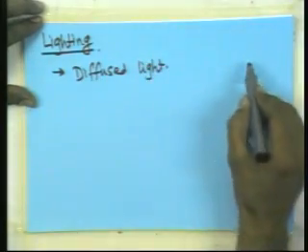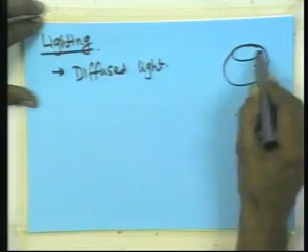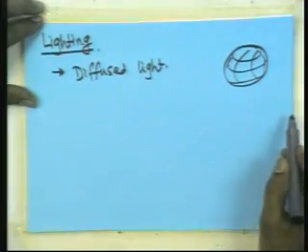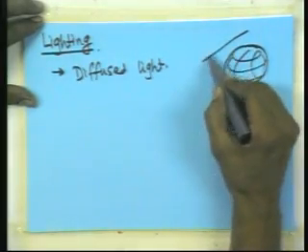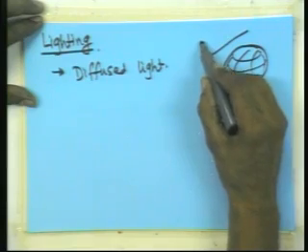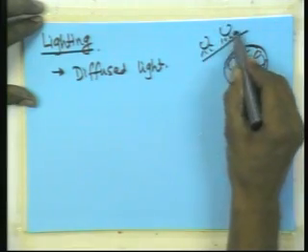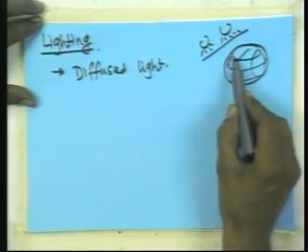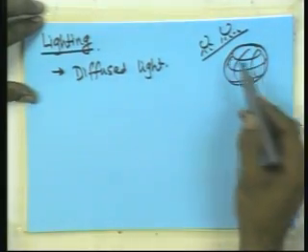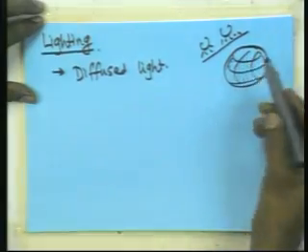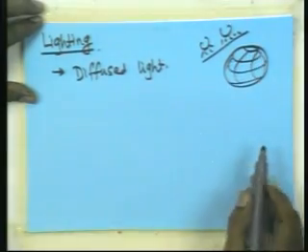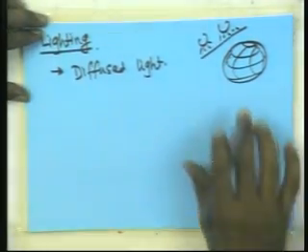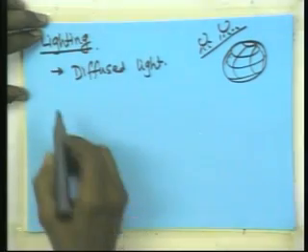In diffuse light, let's say you have some object with some continuous curves. I diffuse the light, so I don't use a light source directly. I may have a ground glass here, and then I have light sources behind it, so that what I get here is a diffuse light. Then I will see continuous change in intensity because of the surface features or surface curves, and that will be useful for looking at objects when we want detail of the overall surface or the curves of the surface.